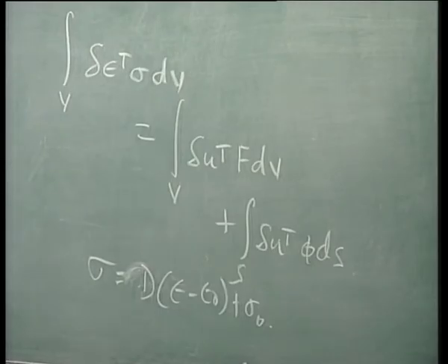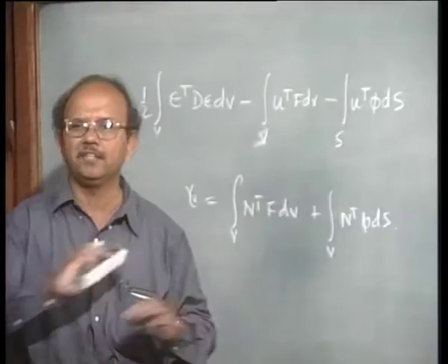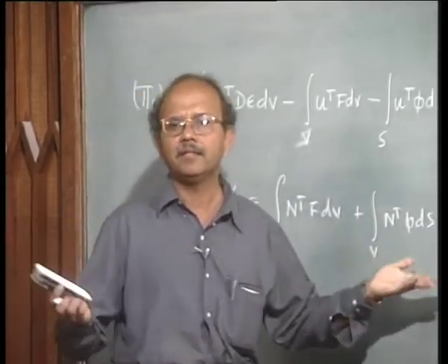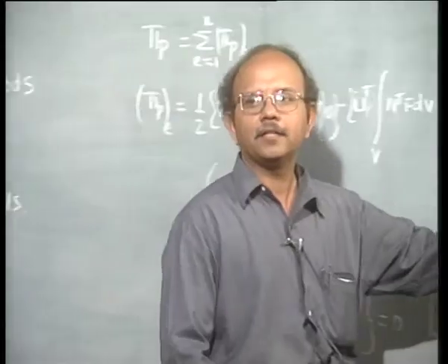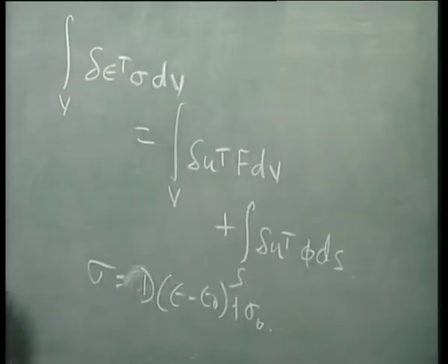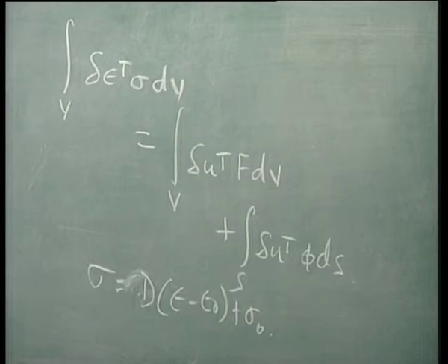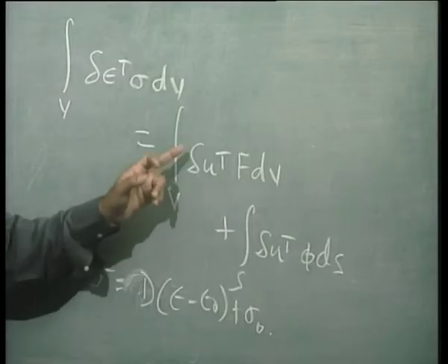So, what do you get? The equation will be delta d transpose B transpose D B d, small d. So, B transpose D B is what? You should just get it into your system, B transpose D B, what is that? K, that is it. So, you get the stiffness matrix straight away from the first term. Any confusions? What is the second term here? Delta u transpose f.